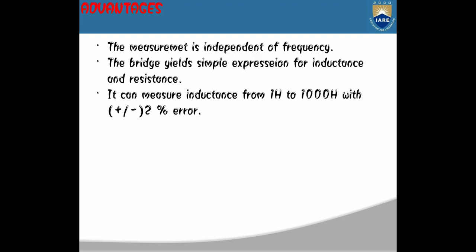The Hay bridge is used to overcome the drawback of Maxwell's bridge. This bridge circuit is used to measure a high quality factor in a circuit. Thus, this is all about an overview of the Hay bridge. The quality factor can be measured by using Maxwell's as well as the Hay bridge, but Maxwell's is used to calculate medium quality factor, whereas the Hay is used to calculate high quality factor. So, to overcome Maxwell's limitation, this bridge circuit is used.